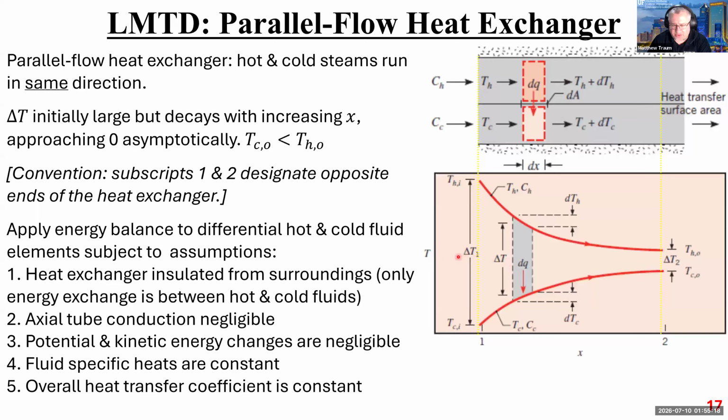If this were allowed to be really long, these two temperatures would basically become the same temperature if you had a really long distance for that. The other thing I want to point out, because it's maybe a little distracting, is that I've got these yellow dotted lines in here. That was just for me to line up the start of this figure with the start of this figure, so that you could see that as you march through the tubes, the temperature of the hot side does actually cool down and the temperature of the cold side does actually warm up. And they reach this very slight temperature difference at the end when they exit the heat exchanger.